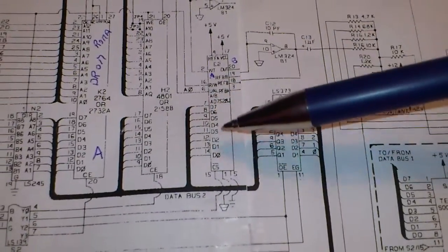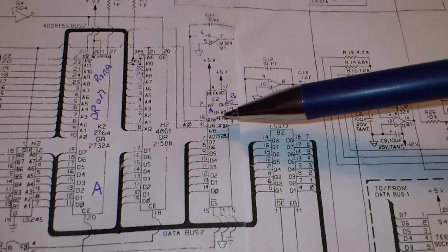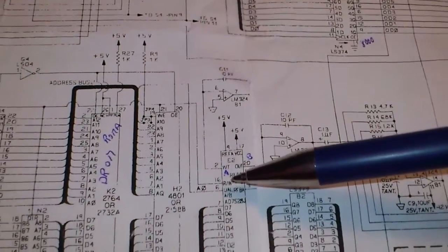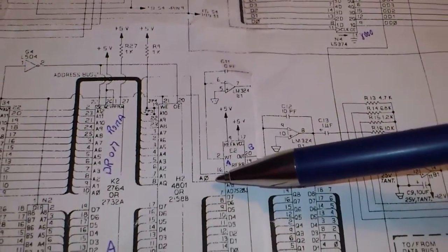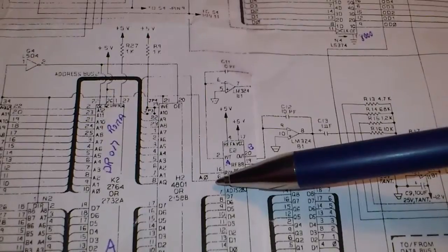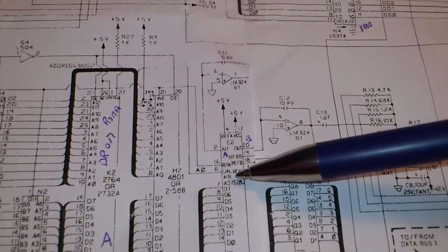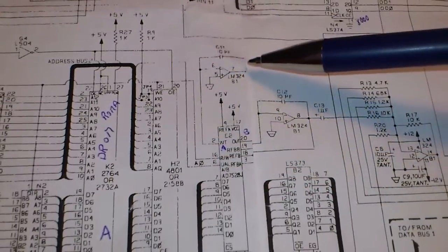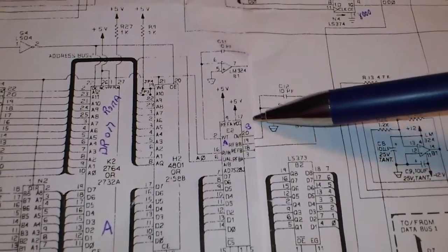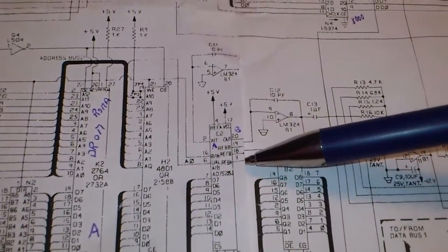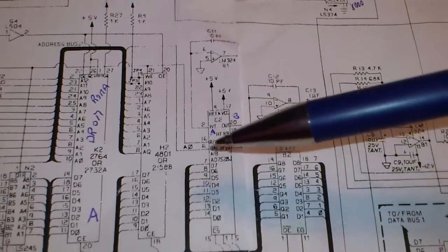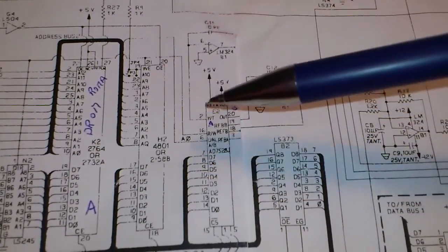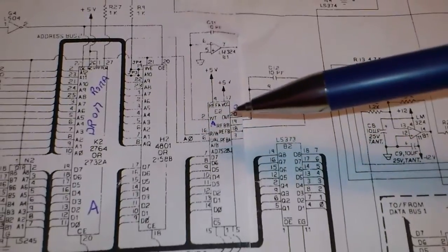That is a 2-channel device, and there is a little bit of a caveat on that one, because what you see is that the A0 line is selecting between the first DAC or the second DAC. And you see that the first DAC is actually setting up, with that amplifier, a reference voltage for the second one. So what that means is that you can set up the amplitude for the second DAC.